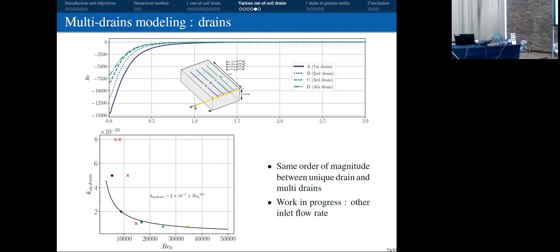Right. So did you use any turbulence modeling technique? Yes, in this case it's a K-omega SST model. Okay, right. Another question is the porous media source term that you have added. You didn't incorporate the effect of porosity in the convective term and in the temporal term. Did you consider the effect of the porosity term, epsilon, other than the FD option? The porosity of the media, no, because we have it through the permeability.